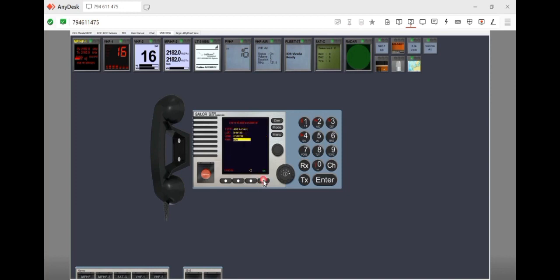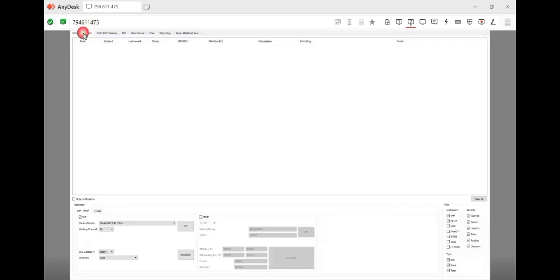So we need to choose the radius of the area where it is to be sent. If you want a specific ship, you need to send the MMSI of the specific ship. For example, this is the MMSI. Press OK. So you need to choose SSB telephony, then the nature of distress of the vessel in distress. For example, sinking. Press OK, then press send, then press yes to send. The instructor is going to check now if it is successfully sent.